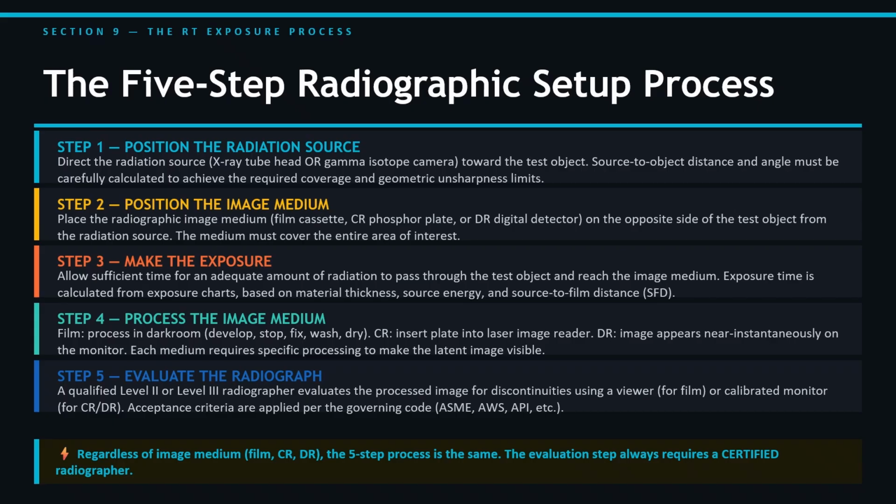The qualified interpreter must determine whether the image meets the required quality and whether relevant indications are present. Then the appropriate acceptance criteria are applied. So, regardless of whether we use film, CR, or DR, the fundamental logic remains. Position, expose, acquire, process, and evaluate.